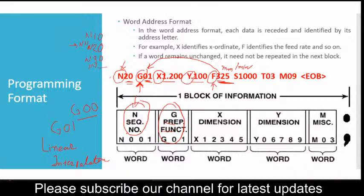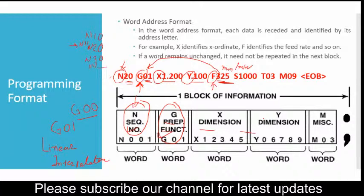Now the sequence number and the preparatory function are clear. Then we will be having coordinates X, Y, and Z. Our turning center is having only X and Z. It does not include Y. So we should be writing X, which is preceded by certain coordinates, or Z, which is also preceded by some coordinates. Then if the number is preceded by F, it stands for feed rate.